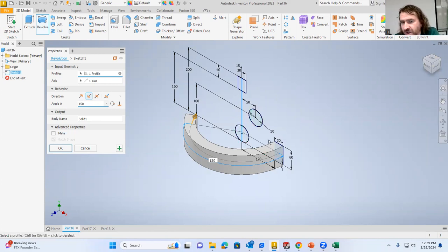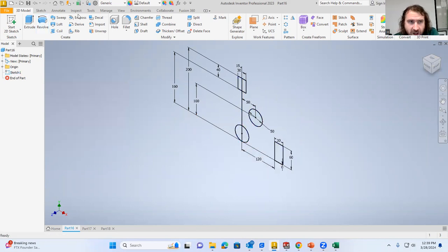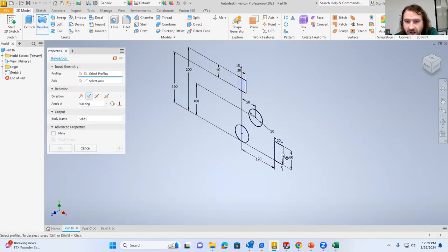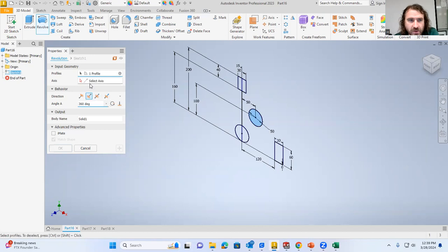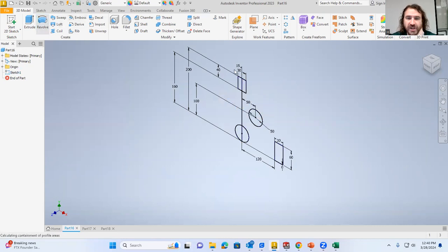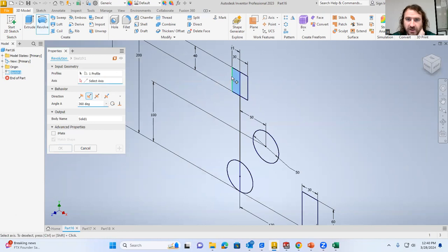So this is the Revolve tool, using profiles, using these shapes, and an axis of revolution. You've got to use the two together in order to get the design intent of whatever it is you're creating with that revolve tool. It's very, very useful for objects that have symmetry at a center line axis, like a cylinder type of shape, or anything that has symmetry on a midline. Look at revolve as a possible option to solve those problems.